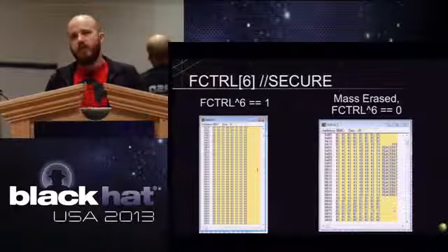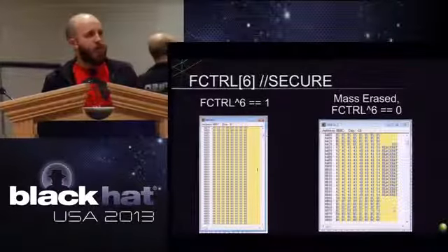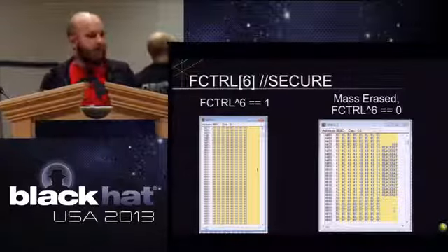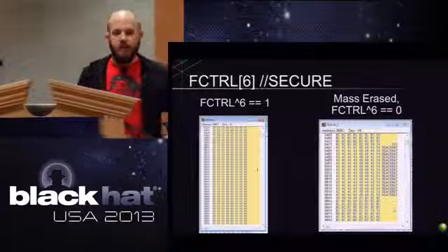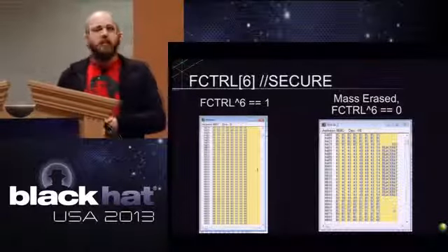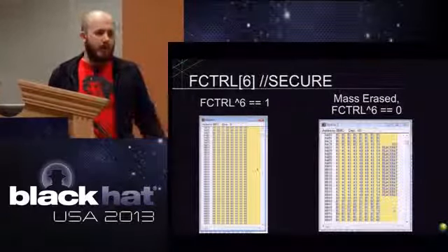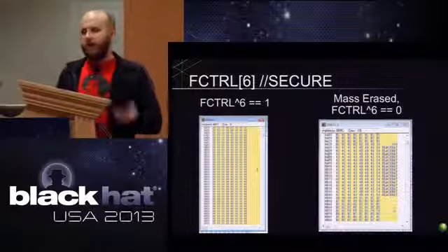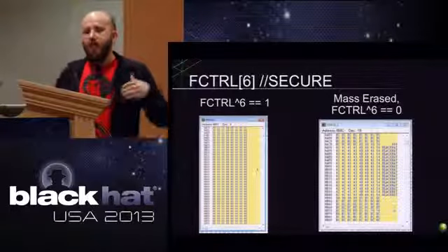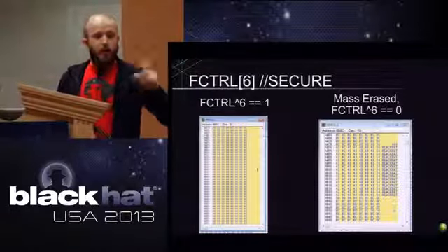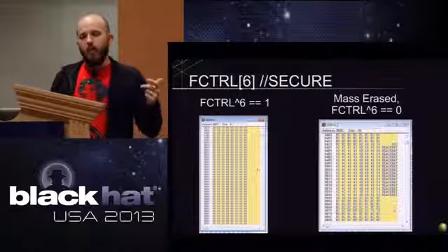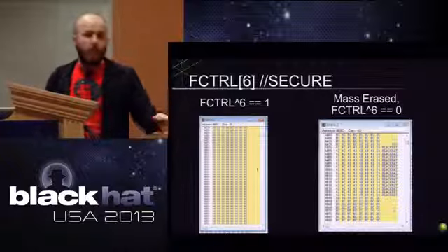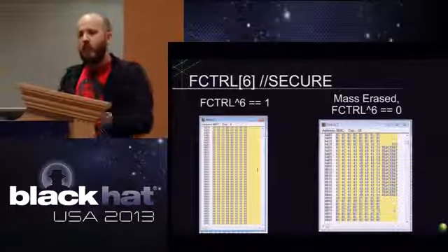This is like being able to see RAM without being able to see the code. So you don't necessarily have any context to know what these things are, outside of knowing what the device does. Let's say it's a smart meter, and it's doing encryption as part of an ANSI standard. Well, you know certain things about how that's going to work: what type of encryption it uses, what its key sizes are, things like that. And coincidentally, the way that's implemented in code will most commonly require you to copy that key out of code memory into RAM to then perform operations on it.